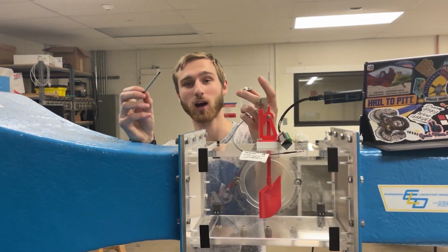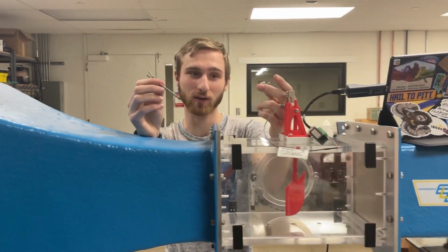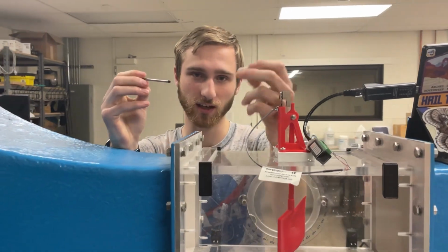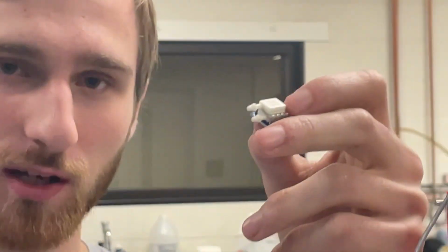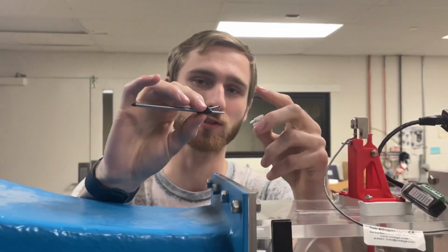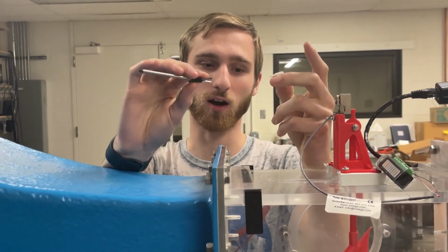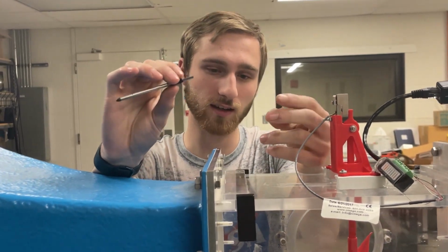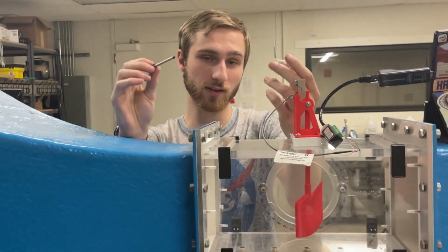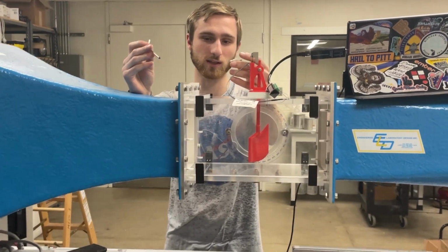The story with our velocity sensor was quite a mess. It was very different here. So our original sensor was this guy. It was a little DP sensor connected to a pitot tube, which basically measured the difference in our stagnation pressure and our static pressure and gave us basically our dynamic pressure and our velocity. So actually, we got rid of this because it had a bunch of problems with its digital readings.